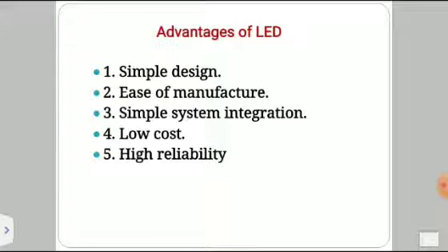If you take up an LED for establishing any optical link, it is very simple. You can easily design it, easily install it, and it is easy to manufacture. There is not much problem in fabrication. It is already well advanced and easily available, with simple technology and simple system integration compared to the LD. The LD is very complicated and extra care must be taken, but for the LED simple system integration is sufficient.